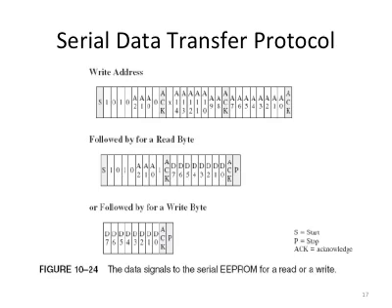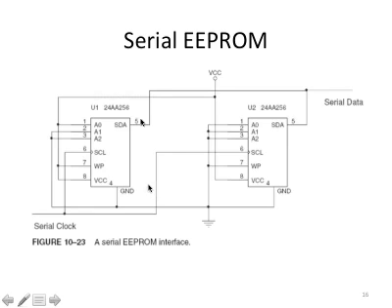What's the difference between the first A0 to A2 and the second A0 to A14? Okay, so this A1, A2, A0 is the identifier of that chip. Let me go back to this previous slide. So the first A2, A1, A0 are used to identify one of these chips. And once this chip is identified, the next series of address bits are used to select content within this chip.